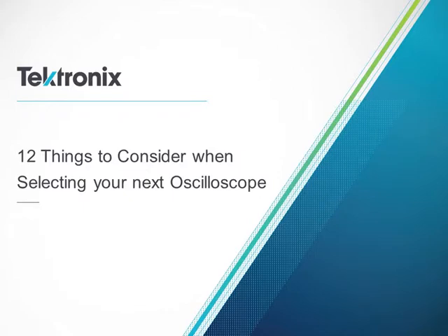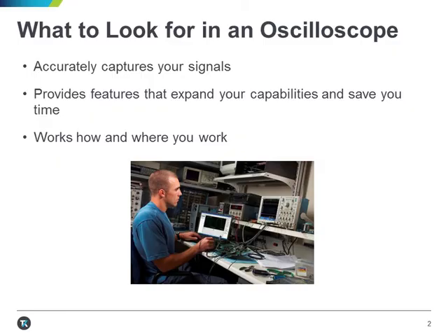At the end of this session, I hope you'll come away with a better understanding of scope specifications and what kind of features are available in today's instruments. This session is geared towards choosing a scope for your bench, when and where you'll likely be doing most, if not all of the research on your own. If you're considering a scope with a bandwidth above 1 gigahertz or for a special purpose testing application, you should probably talk to an application engineer at Tektronix to help you make the right choice.